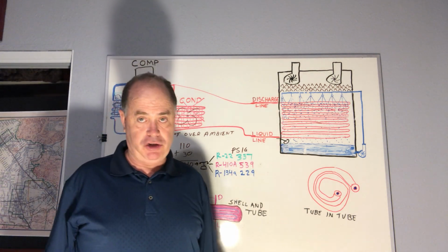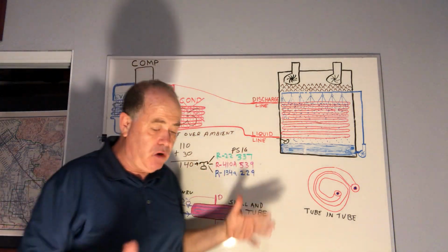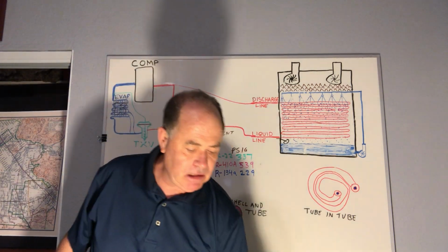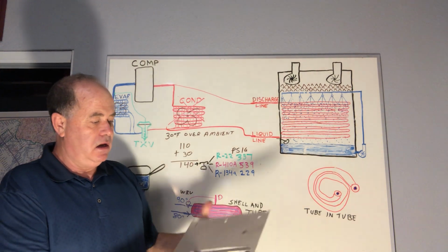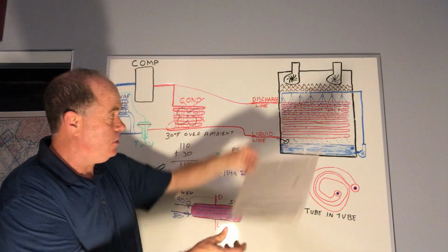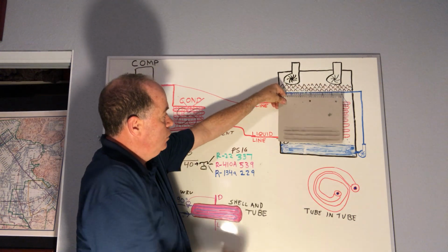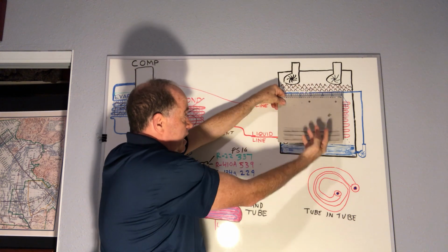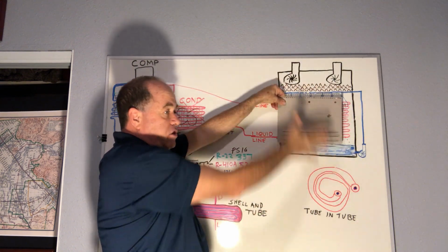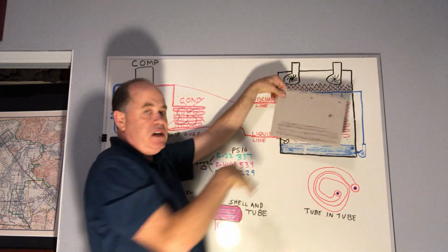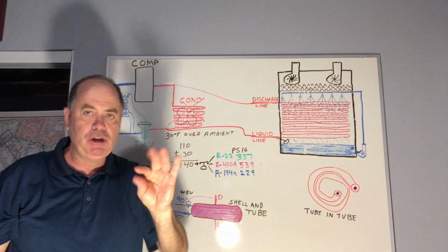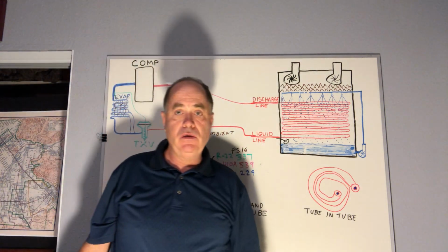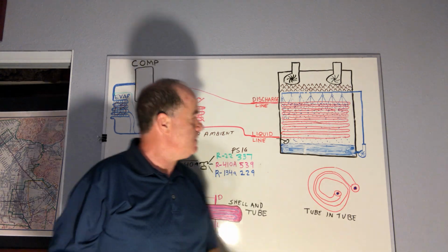and lowers the head pressure. Now, it's also drawing air inside, and it really has something like this. Obviously, this isn't exposed to the atmosphere. You have something like this, where you have louvers at the bottom that allow air to be drawn in by the fans, and then as it passes over the water, some of that water evaporates and you see what's the proper term, a plume, that fog that comes off the top of your evaporative condenser, also an appropriate term for cooling towers.